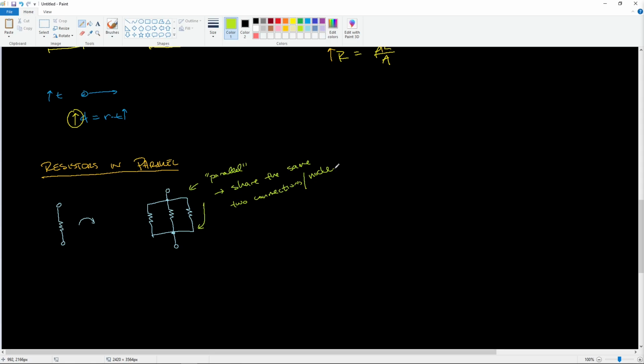Last video we talked about Kirchhoff's voltage and current laws, which I misspelled. Looking at junctions, a junction is considered a node, and those are just points of connection between different elements or branches in your circuit. Visually it can be hard to deduce what's in parallel sometimes, but as long as you can see that they're both connected and sharing the same two nodes, then they're in parallel. Then let me put little resistance labels, just R's. We could say that they're all the same. They might not be, but they could.